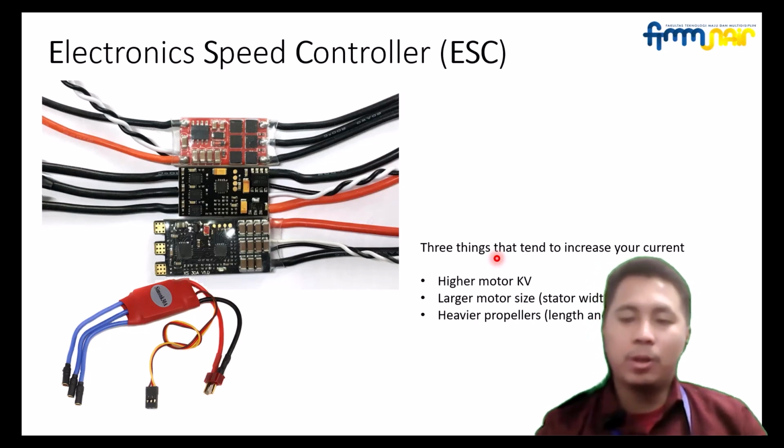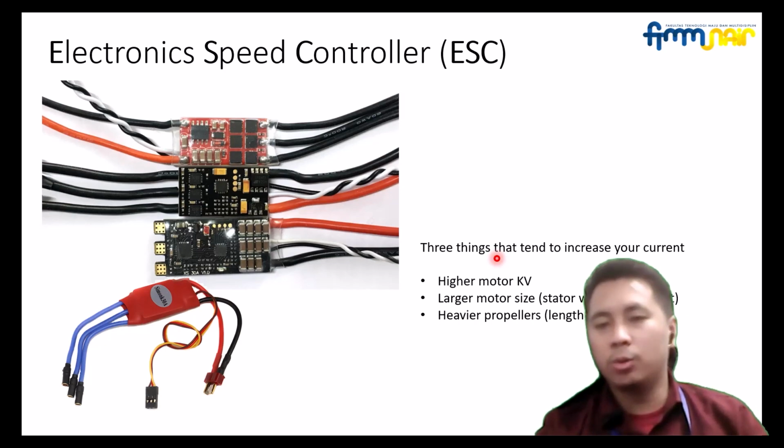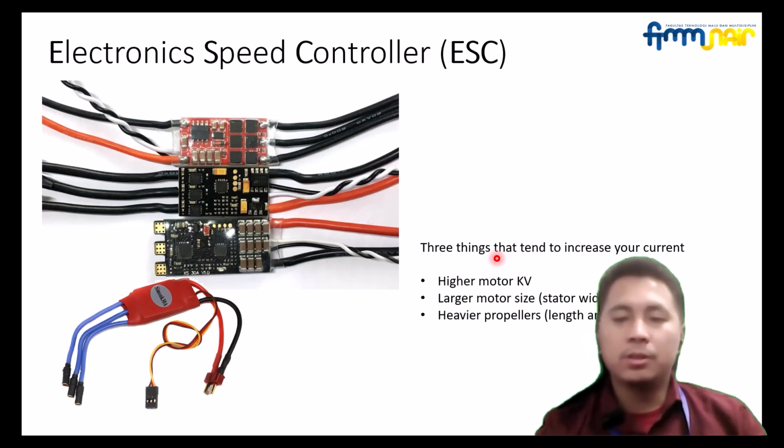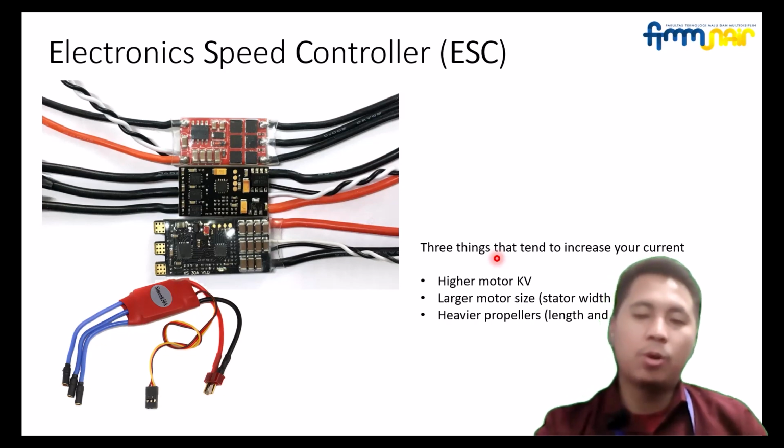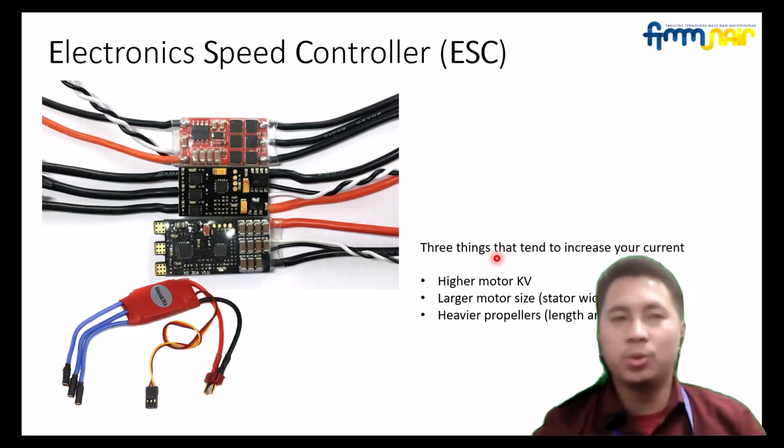And heavier propellers also draw higher current. The key point in deciding the electronic speed controller is the current drawn by one rotor or one motor.